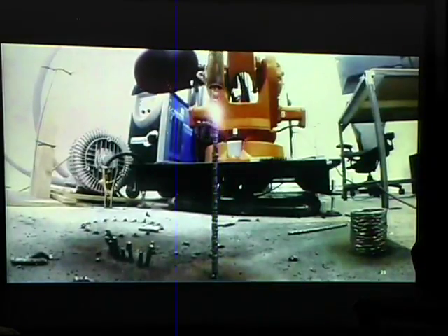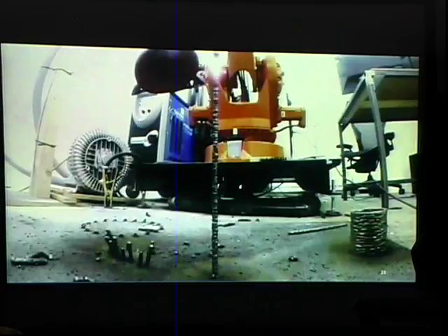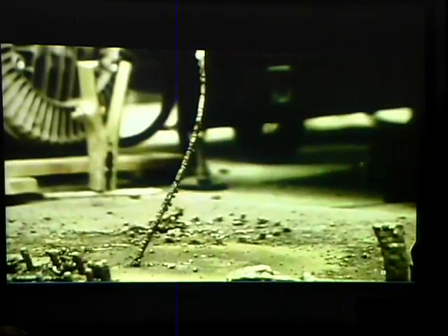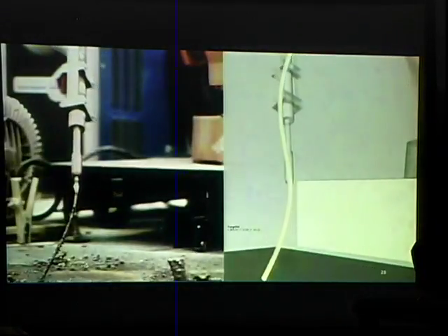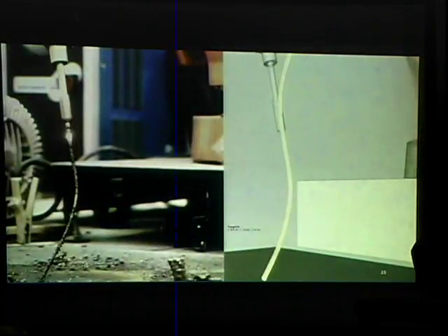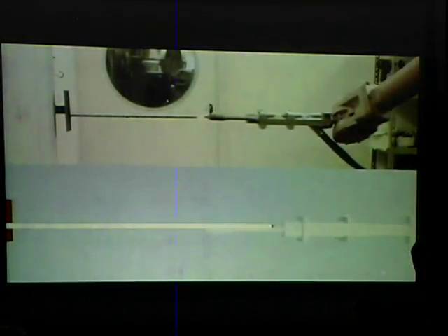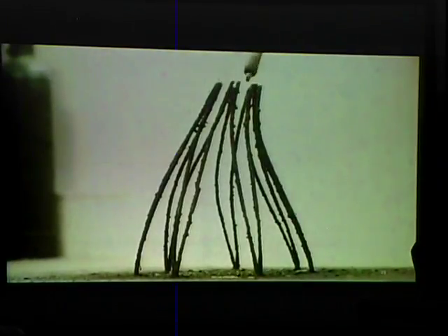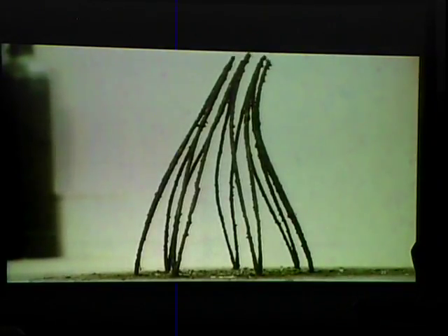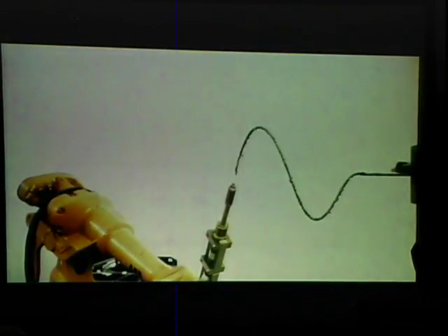You don't have to make really boring basic shapes either. You can get a robot arm, which robot arms run on G code too, and you can print or just have it move in 3D space. So we can see it's kind of printing a freehand arc right here. And what you see when you put it side by side with the CAM software is all it's doing is tracing and replicating that path. It's really an API to communicate between the CAM software that you guys see on the right, I gotta do left and right here, and what you see the machine actually executing now on the top. So that's the advantage of the CAM software, right? It's a very, very visual way of coding for something that ends up being real and physically manipulable.